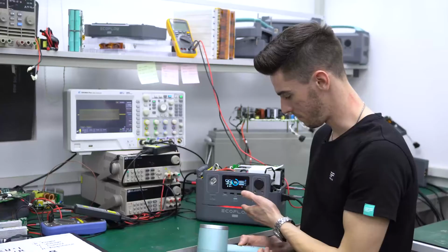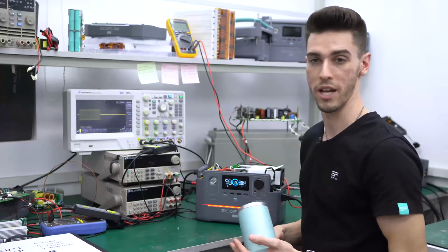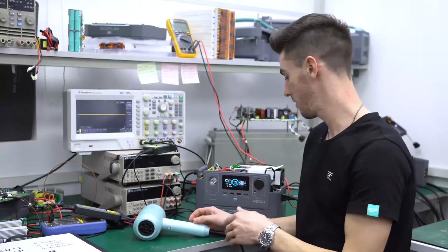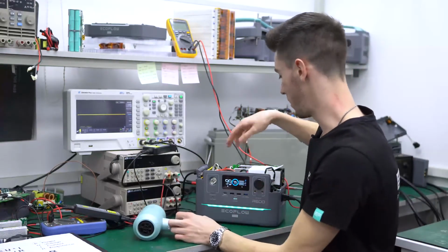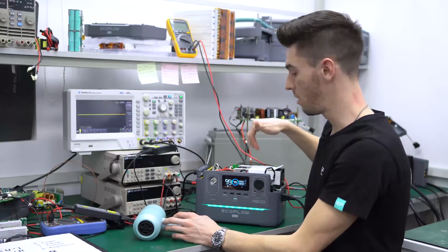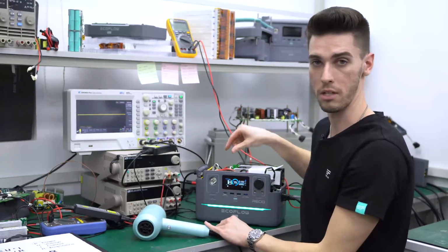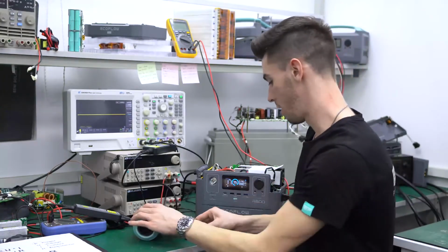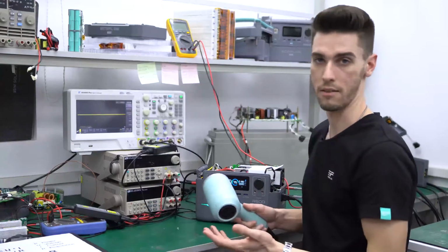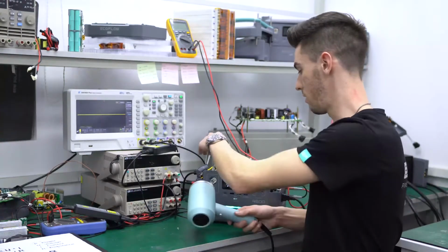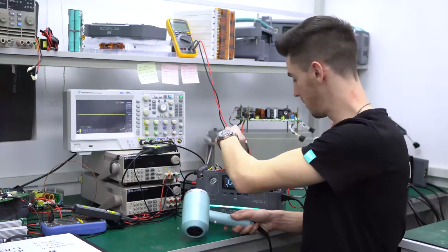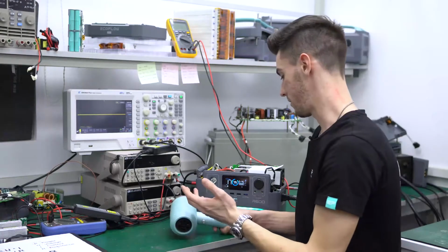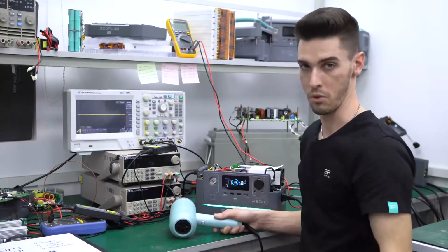Okay, so this triggered the overload protection system. This is actually a key safety feature that we've implemented to keep you and the device safe, because when this device is in extreme bypass mode, we don't have the ability to control the voltage like we do during the X-Boost feature, the X-Boost mode. So what happens is this 1200 watt device is going to try to pull as much as it can from the AC input. This could damage the electronics, possibly cause a fire. So the reason this safety feature was implemented, again, is just to keep you safe, keep the device safe.